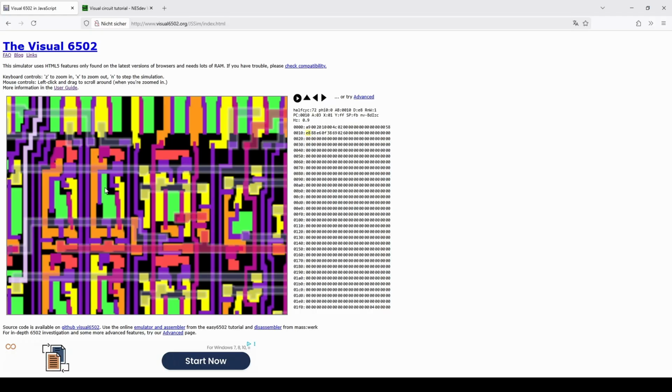This will increment x from 1 to 2, which means bit 0 will be cleared and bit 1 will be set. So if we step this through again, once again, we see the value in this x bit 0 being put onto the special bus. I hope I always called it the special bus previously, but yeah.